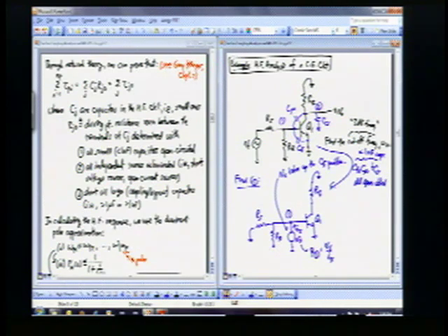So I've converted that to this circuit here. And now I could go ahead and push a voltage and measure currents, but I know what this driving point resistance is right at this point. And so do you. You could do that just by inspection. So can someone tell me what that is? What is that resistance seen right at that node? R pi in parallel with RS parallel RB. Exactly. So R pi parallel RS parallel with RB. Okay, that's my driving point resistance.